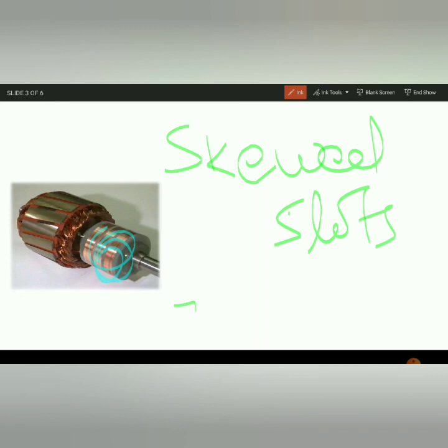The rotor will not be able to rotate due to equal magnetic fields from both the stator and rotor. The two forces cancel each other and there won't be any net force, so the rotor will not be able to rotate. This is another point of construction in the rotor.